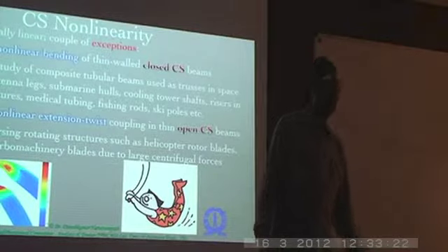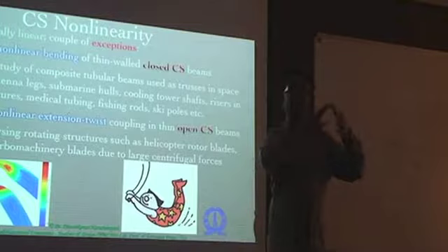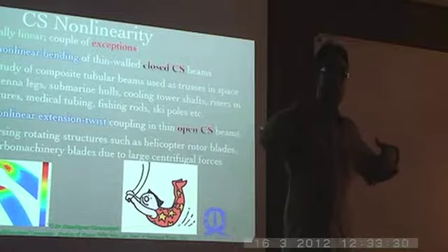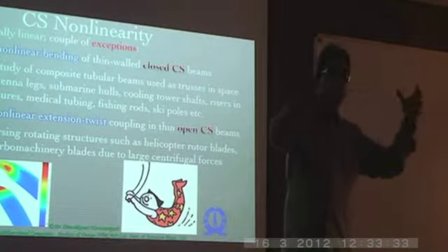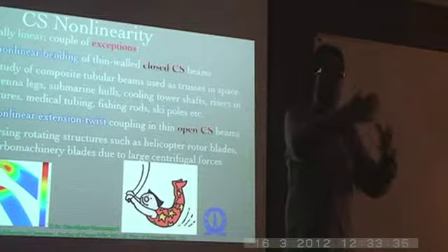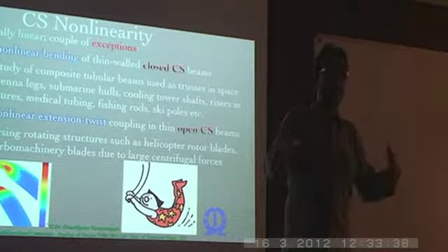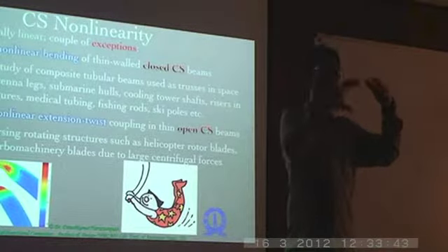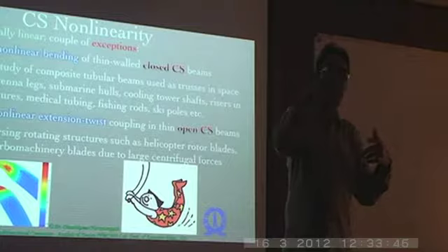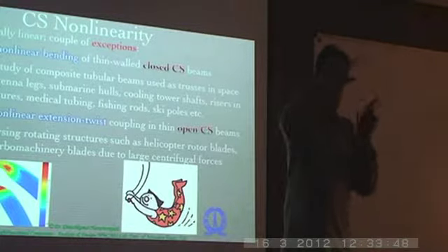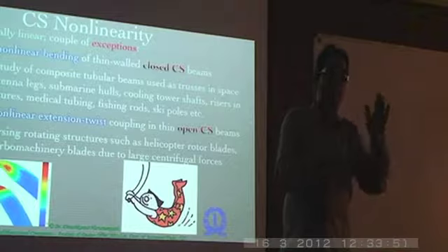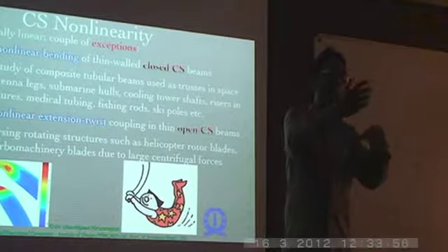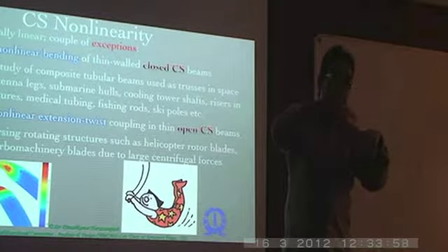See, basically there are many different ways of analyzing an aircraft wing. Either you can treat the entire aircraft wing as a single beam with a particular loading, which is the equivalent loading coming from the aerodynamics and the weight and all the other engine, etc. Or you can treat each one of these components separately. So you can treat the spar separately, you can treat the stringer separately, you can treat the skin and the box beams which come because of the spar webs and the skin, all those separately. So when you're doing that, of course you have to look at the interfacing loads which come because of that.